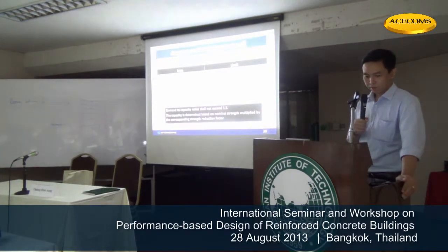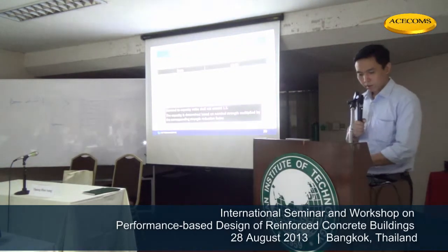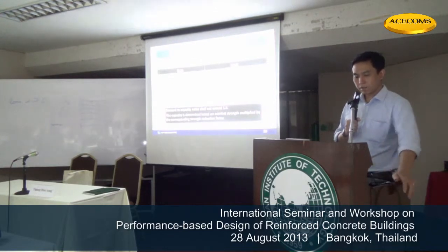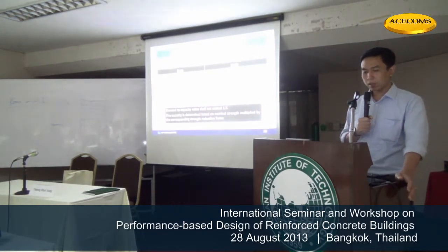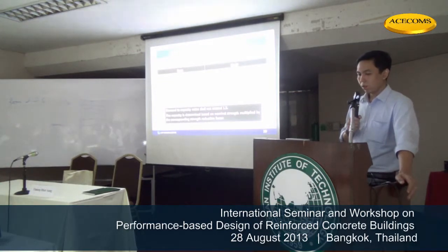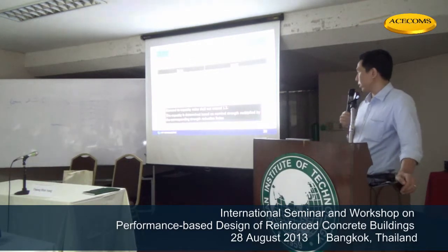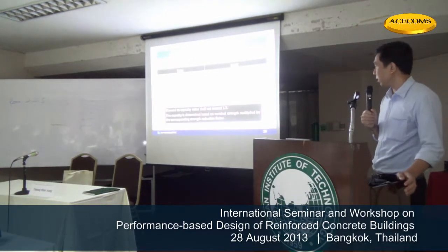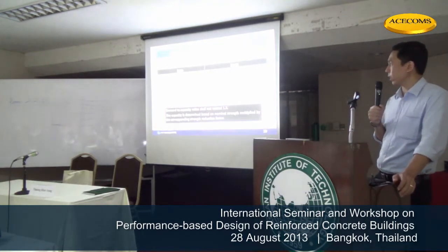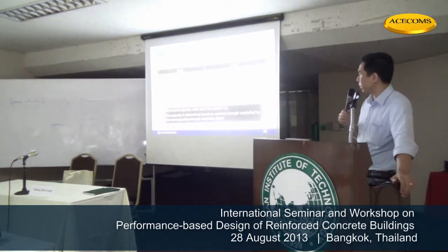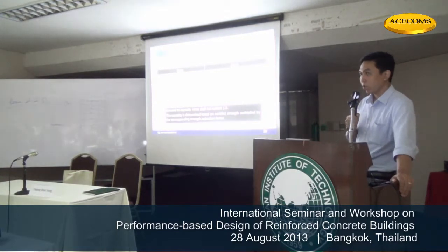For residential reinforced concrete buildings, normally when we check the building weight, it is about 1 to 1.5 ton per meter square. So if you calculate the weight of the building and then divide it by the total floor area, and it is coming out 4 ton per meter square, something is wrong in the load assignment. We have to check carefully.